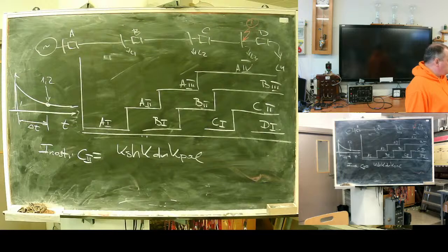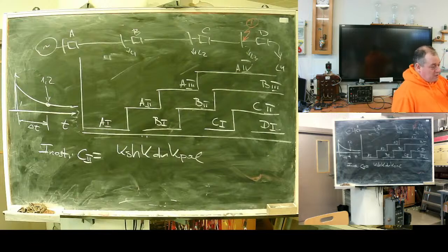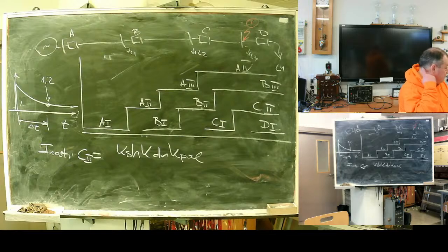Also, what you can do is create two zones with close trip times. The first one with a longer delay, some 30% more, in my case, let's say 1.5 delta t.